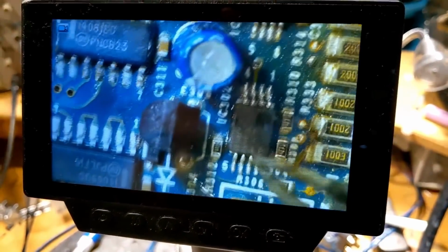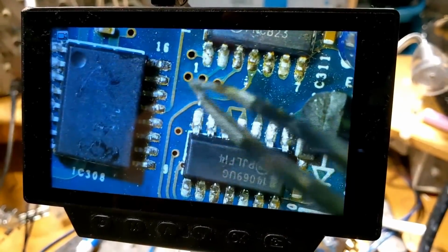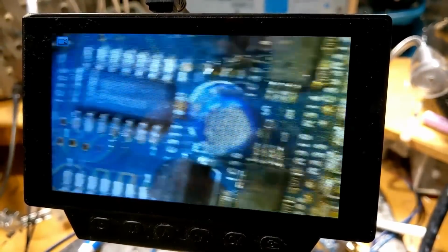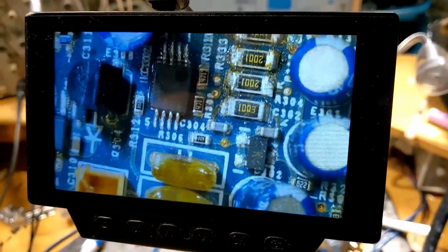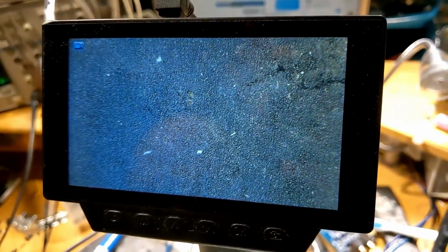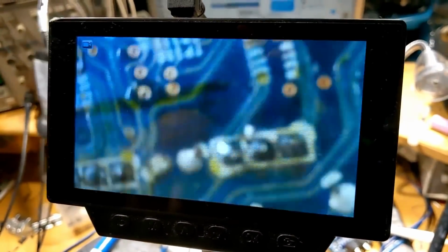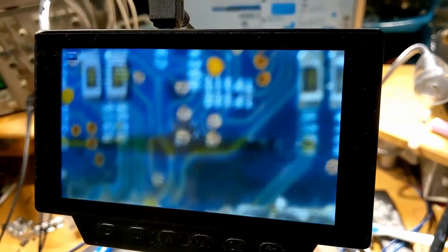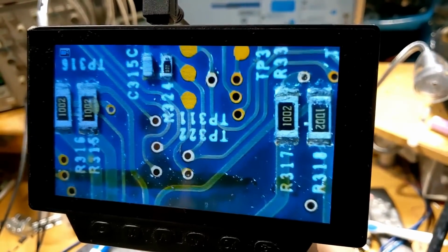And then I still wasn't getting any drive input to the drive ICs, and this was a big head scratcher. I went around the whole board for ages. I found some more stuff on the bottom of the board. Over here, there were some resistors over this side that were completely failed.